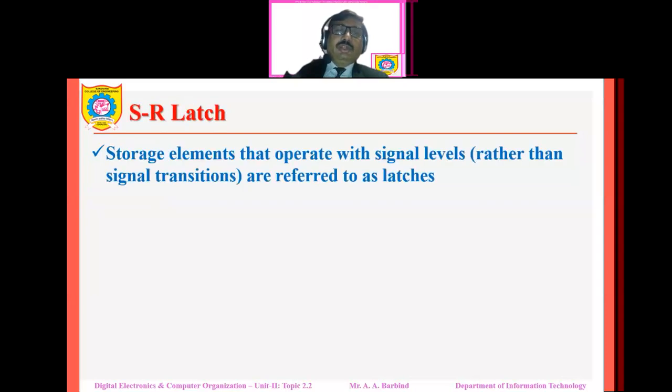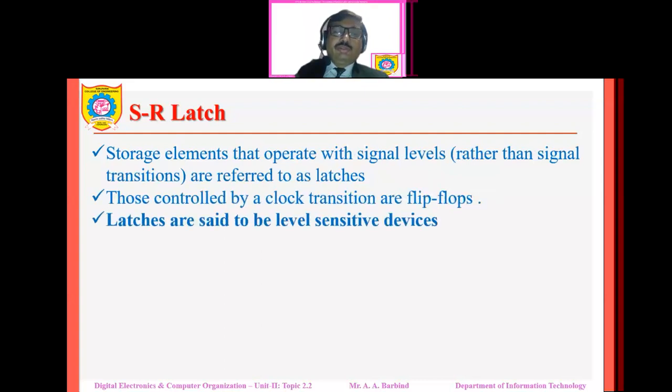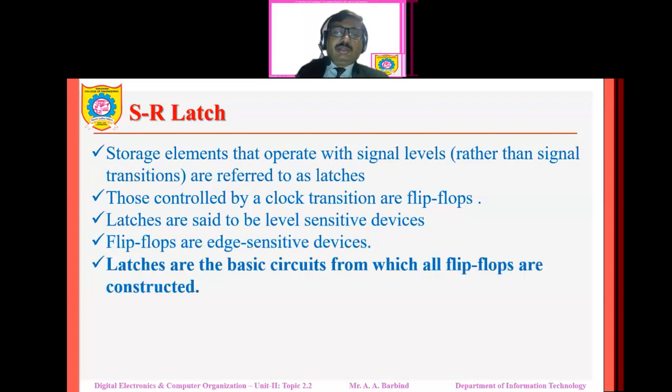So what is SR latch? Storage elements that operate with signal levels rather than signal transitions are referred to as latches. Those controlled by a clock transition are flip-flops. Latches are said to be level-sensitive devices. Flip-flops are edge-sensitive devices. Latches are the basic circuits from which all flip-flops are constructed.